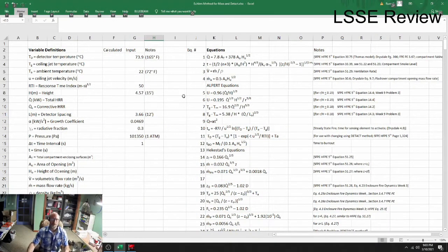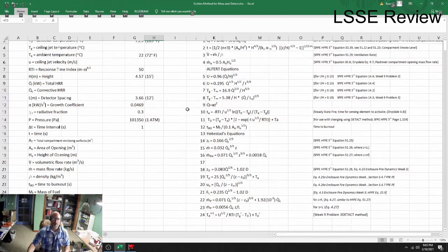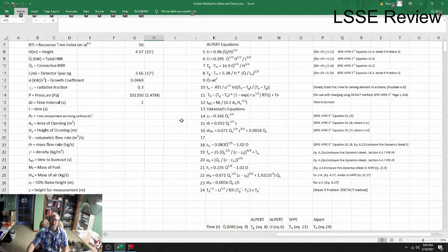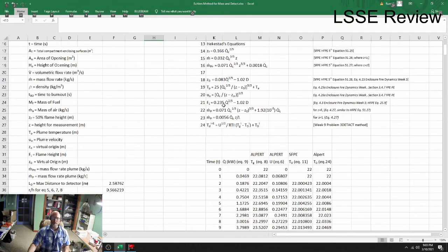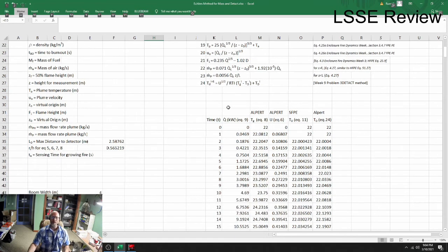Okay, so I just wanted to show you how to actually implement your equations, how to actually perform the calculations. And what I think the videos that we've looked at here show you is there's a lot of variability. And the reality is formulas associated with fire protection engineering, due to assumptions, things like that, really are only designed to get you about an order of magnitude as far as accuracy. I think even mechanical engineering, any engineering field, your target's about 20%. But fire protection is particularly challenging because the form factors of your material is challenging.